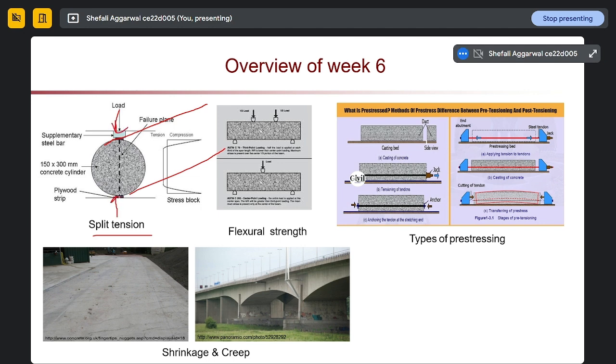So we are using the normal compressive strength testing machine, and we will fill the mold with all the aggregates, mainly coarse aggregates, and then we will determine the crushing strength value of this. Then we have the modulus of elasticity. Other than this, we can calculate the hardness, impact value, and the crushing resistance of our coarse aggregates. And in the same way, specific gravity and the different gradations of our aggregates.